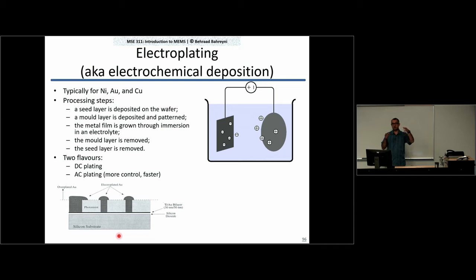So you remove a little bit of material from, let's say, let's look at the substrate side. You deposit a little bit of material here, then you reverse the current and you remove some of it. And then you deposit more and then you remove some of it. And on the source side, it's the opposite thing. You remove some and then you put some of it back. The substrate side is where we are interested in.